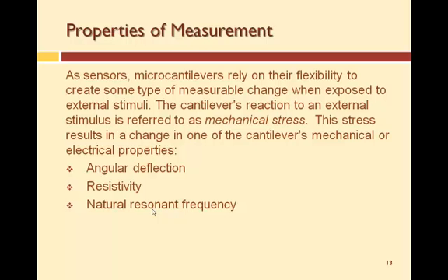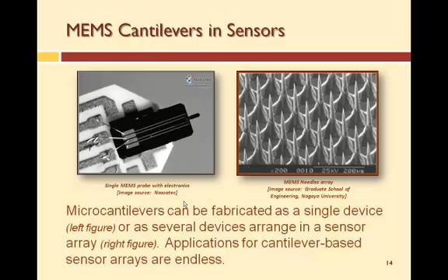So if you can look at the natural frequency or the vibrational frequency of the cantilever, you can tell if something has been added to it or not. It'll vibrate slower if it's absorbed something. Okay, so the trick is in the coating, and then how you're going to determine what's stuck to the coating, either by looking at how much it bends or how much it changes its vibrational mode.